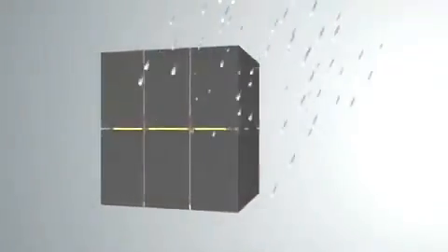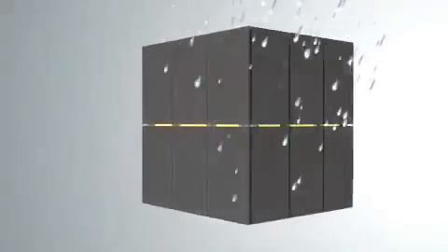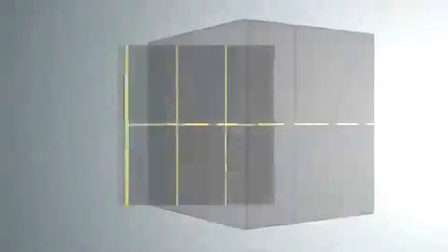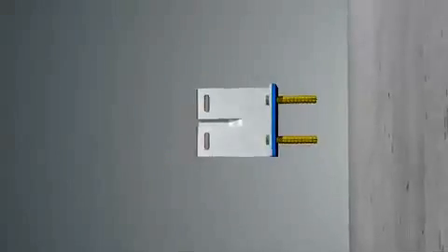The drained and back ventilated rain-screened facades we promote hold the panels away from the main wall. To keep the panels in place, a subconstruction or supporting frame is needed to connect the panels to the wall. Normally, a wall bracket connects the profiles to the wall. The vertical profiles support the panels. This creates a cavity space, which is an ideal position for the insulation.